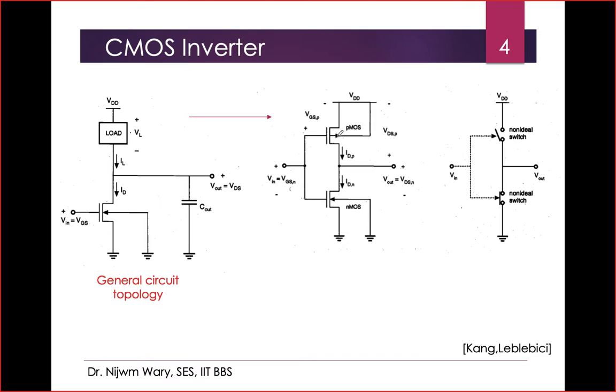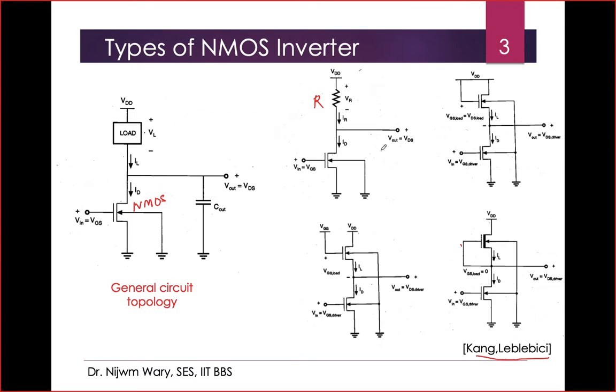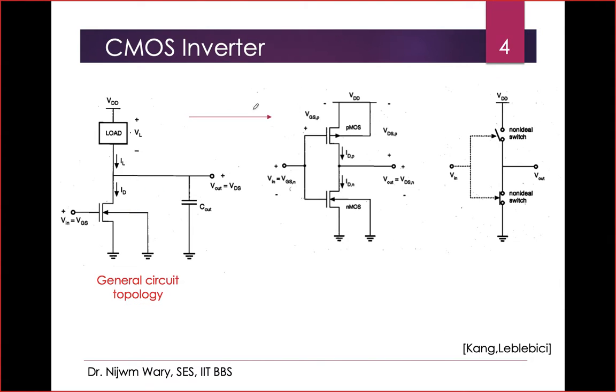device. So you can see the arrow is opposite. In all these cases, the device was NMOS, but here we are going for the CMOS inverter, where you are using both PMOS and NMOS devices. So it's something we can define as a switch, right? Depending upon what the input is here. So this is the final CMOS inverter. Again, the input is applied to both the gate of the PMOS and the gate of the NMOS,